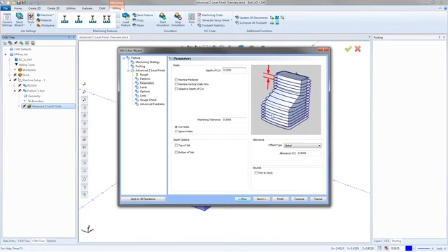The steeper the wall, the better. Now, with the advanced Z-level, you can go past 90 degrees with the vertical on your wall. You can go past 90 and do some undercutting. But with the normal toolpaths, you won't be able to go past 90. 90 degrees is normally the stopping point, because after 90 degrees, your end mill is useless. It can't cut anything else. So this one I will show you an example of an undercut here in 1 second.